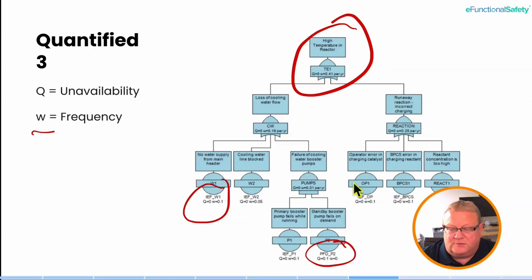In this case, what the tree will do is it will model for the failure frequency, because actually although this unavailability issue is present here, from a frequency perspective, it doesn't impact that W result. So we're either using a fault tree to model for unavailability, or we're using it to model for frequency. And quite often we're looking at modeling frequency to try and compare that with a target frequency of an event to make sure that we don't go over a certain frequency.